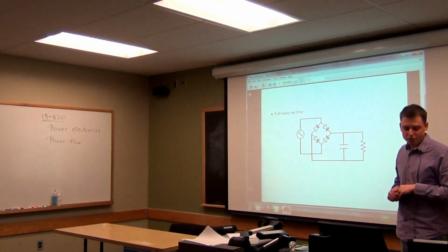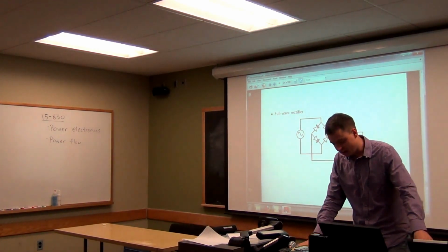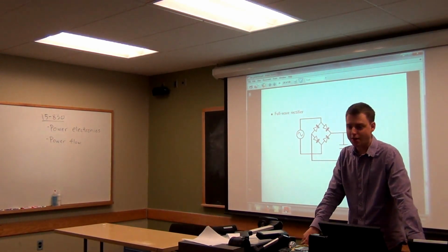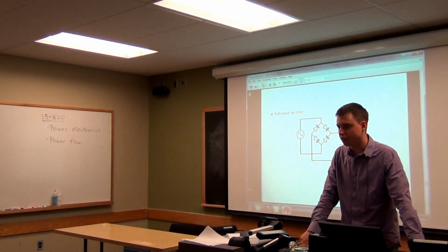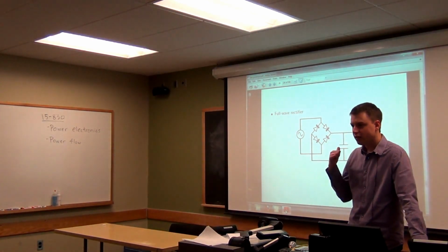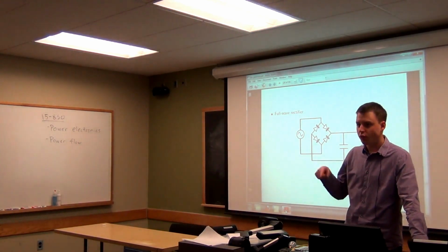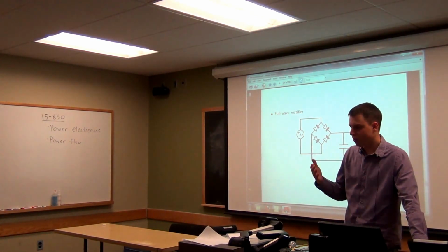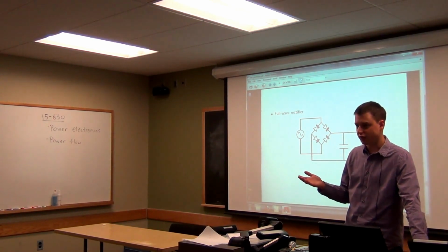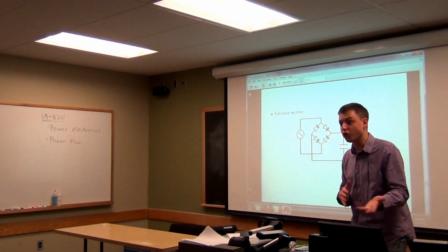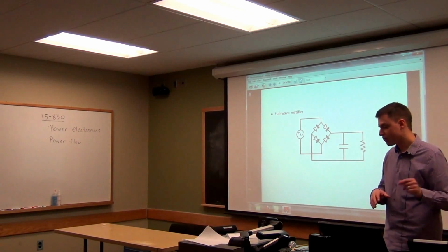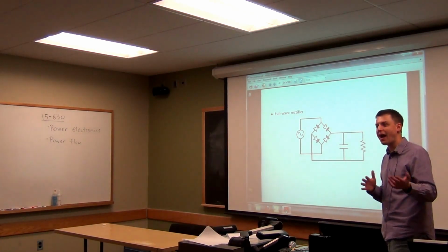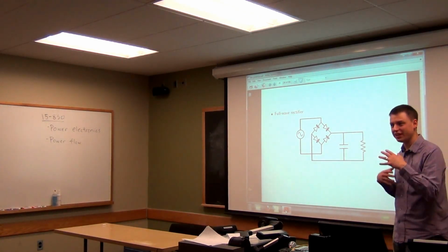And there is more and more, I think, at least at bigger buildings, effort put in place to take waveforms like that and transform them back to sine waves. This is the same thing you had with what we call unity power factor devices, right? For motors, things that use a lot of reactive power, you'd want a device that shifts that back to make it look more like real power. So using a lot of capacitors.